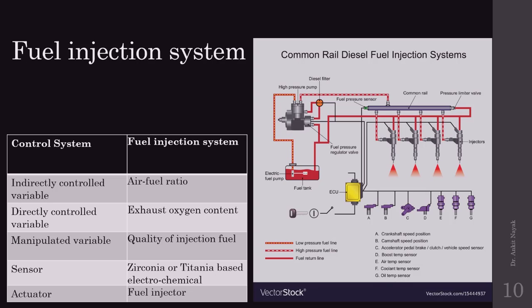At the moment when the fuel or the diesel is injected inside the cylinder head, it will start burning, and the expansion follows the burning. So we have to supply this fuel at the exact time just after the completion of the compression stroke.